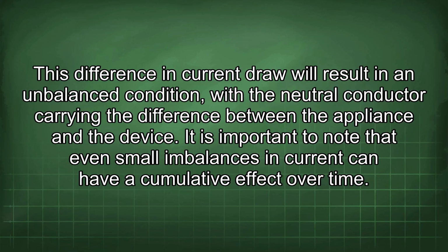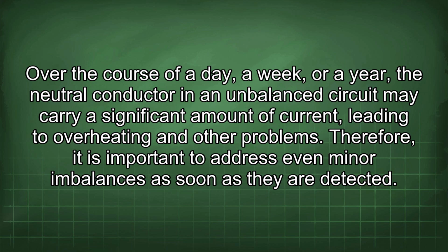It is important to note that even small imbalances in current can have a cumulative effect over time. Over the course of a day, a week, or a year, the neutral conductor in an unbalanced circuit may carry a significant amount of current, leading to overheating and other problems. Therefore, it is important to address even minor imbalances as soon as they are detected.